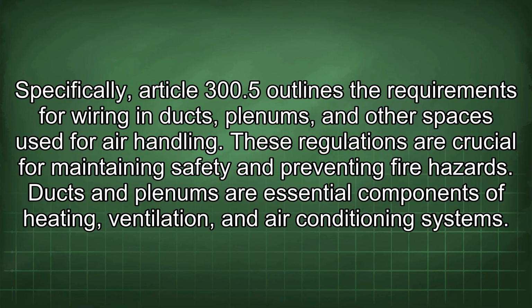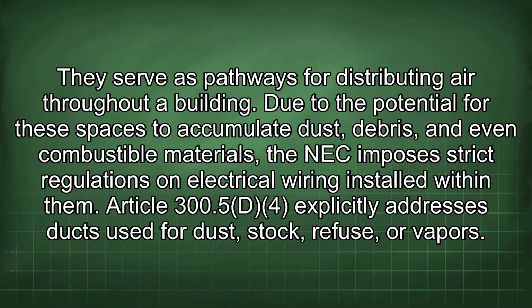Ducts and plenums are essential components of heating, ventilation, and air conditioning systems. They serve as pathways for distributing air throughout a building. Due to the potential for these spaces to accumulate dust, debris, and even combustible materials, the NEC imposes strict regulations on electrical wiring installed within them.